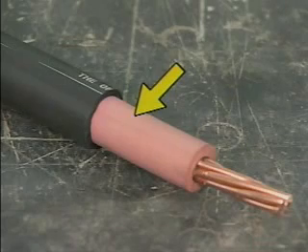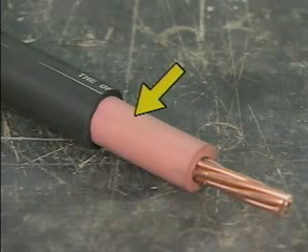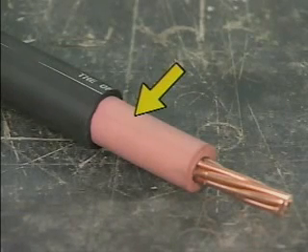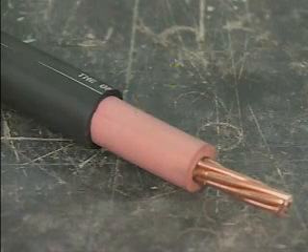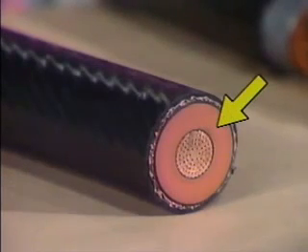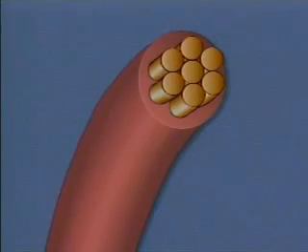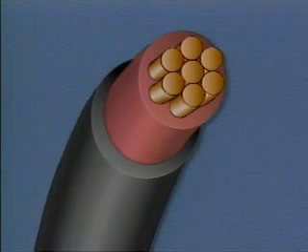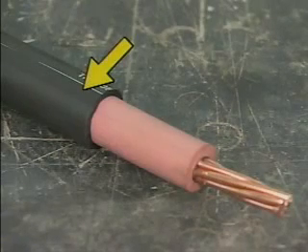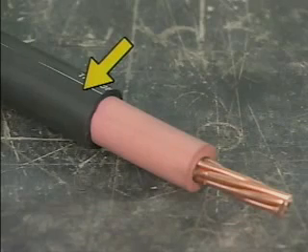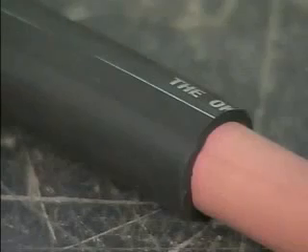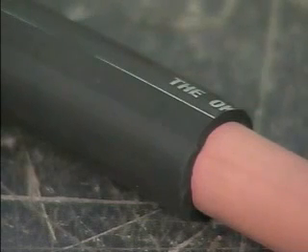A conductor's insulation confines current flow to the conductor's wire and also helps protect the wire from mechanical damage, such as nicks and scratches. In general, the thicker a conductor's insulation, the more voltage the conductor can handle. Some insulated conductors have an outer layer called a jacket. A jacket provides additional mechanical protection for the conductor and its insulation. Jackets, which are frequently made of hard plastic, are common on conductors that must be pulled through conduit. The jacket protects the wire and the insulation from mechanical damage that could be caused by sharp edges on the conduit.